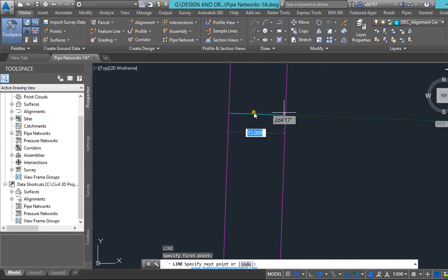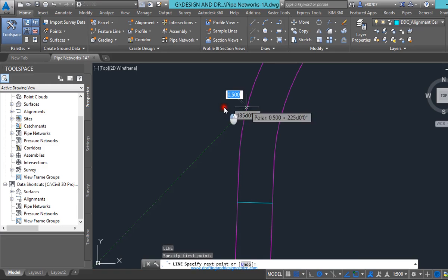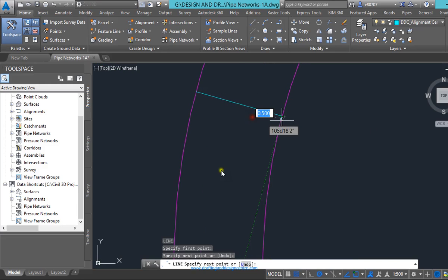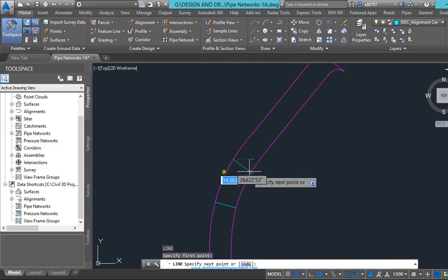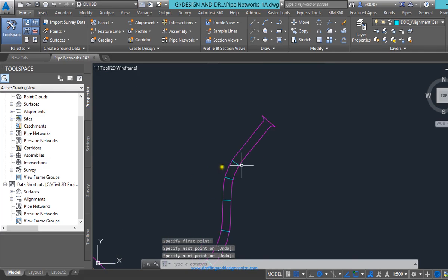When perpendicular is on, you can scroll the mouse and then click it. As you can see, the sign of the snap, which is perpendicular, appears on our screen, and it will snap accurately at that point, perpendicular with respect to the point you have selected.